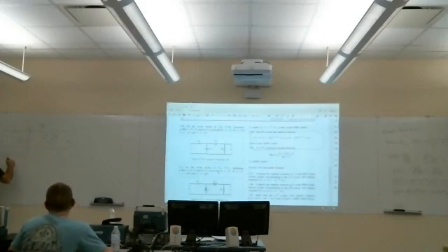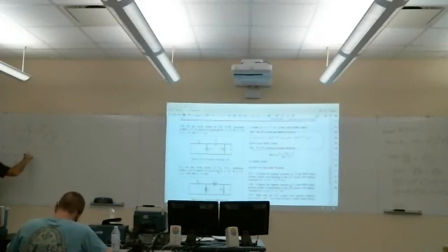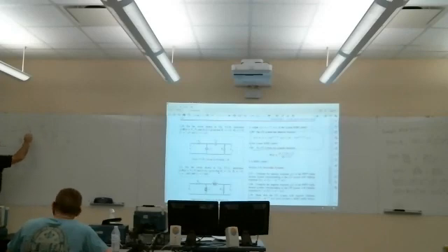Now, Vx is pretty simply this impedance times that current, 10 to the 6 over 2s, plus my output voltage, 2. That's KVL, taking this loop. I'm going to take that path because I know all the currents, and from Ohm's law I know all the voltages.